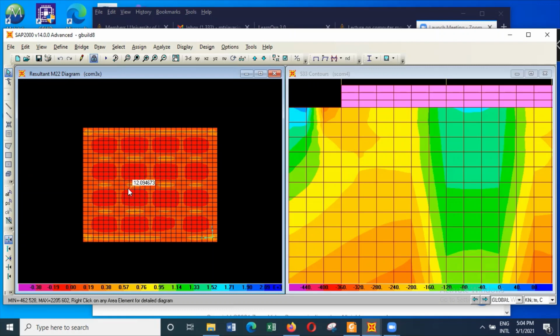So these values are correct, the reason is here we get a rib, here we get a rib, those are rigid areas, and those rigid areas are transferring the loads at concentrated values, whereas these are a slab which deforms more. So because of that, the slab is subjected to a lesser load. So the loads are on the raft, the soil is actually acting with patches, and because of that reason you get under the rib higher stress, within the slab lower stress, and then if you look at the top slab,